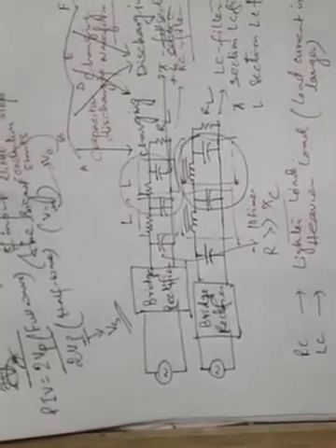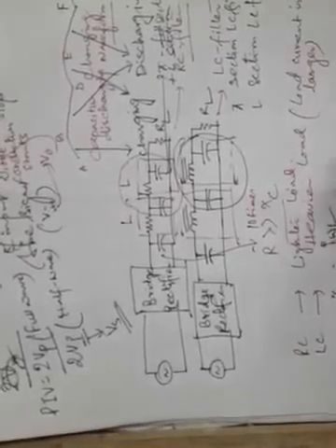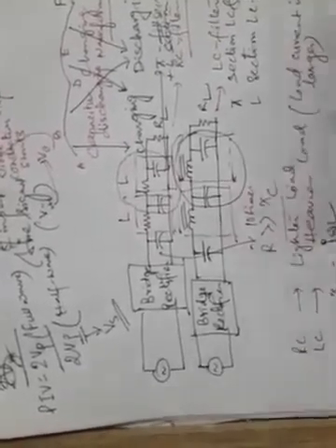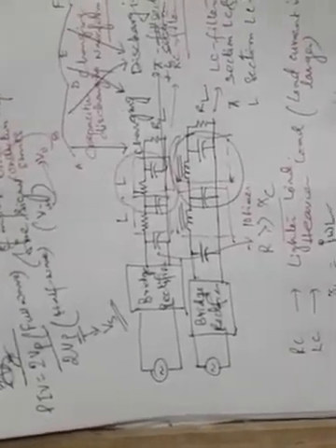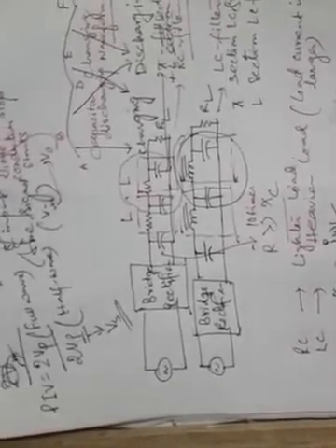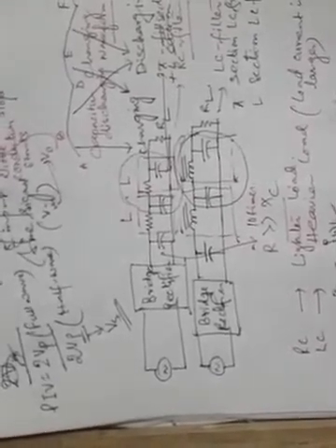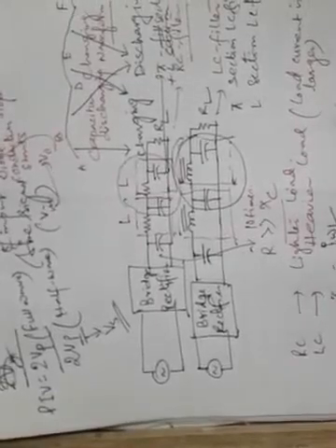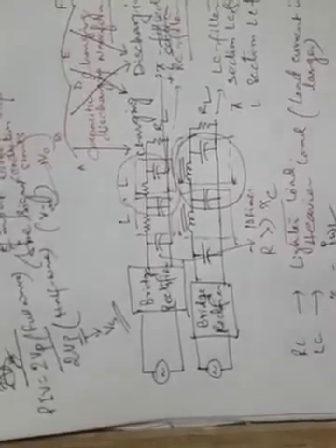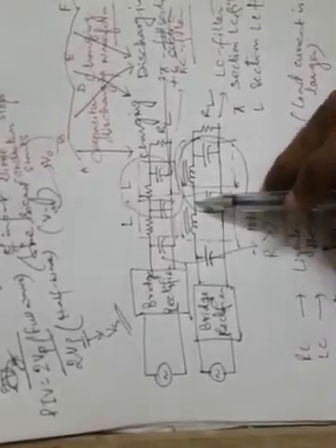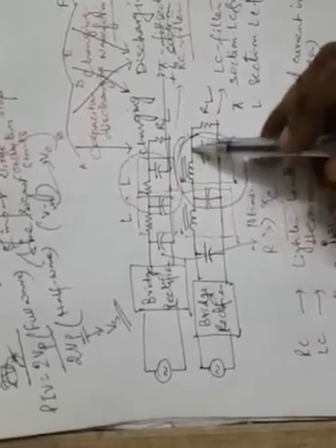So just on the contrary to the use of capacitor in the signal path, XL, the inductive reactance, is j omega L. So as much as the omega is increased, more and more AC signal is being blocked by the inductors. The inductor will pose a high reactance to the signals that will block the signals as much as the signal frequency is higher. So the DC is very well passed through the inductors, but the ACs are blocked. That's why the inductors are always connected in series. That means they will pass DC easily up to the load